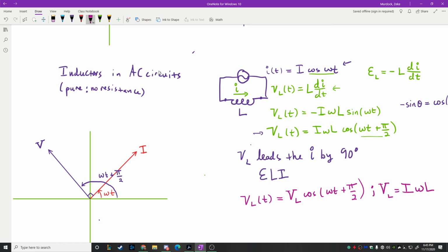And then you look at this equation and you kind of think about what we just did. A second ago, what we just said was the voltage across my resistor was I times R. And you compare these two terms right here and you think, wow, they're really similar. In fact, this whole thing, omega times L, actually has to have exactly the same units as R, right? It has to have the units of resistance. And if you work it out, it does, because 1 Henry, which is the measurement for inductance, is equal to 1 ohm times a second. This is something that came up in a previous chapter. We noticed that 1 Henry actually has the units of ohm seconds. So if you multiply by omega, which has units of inverse seconds, then those cancel out and you get units of ohms. So what we're going to do is we're going to define